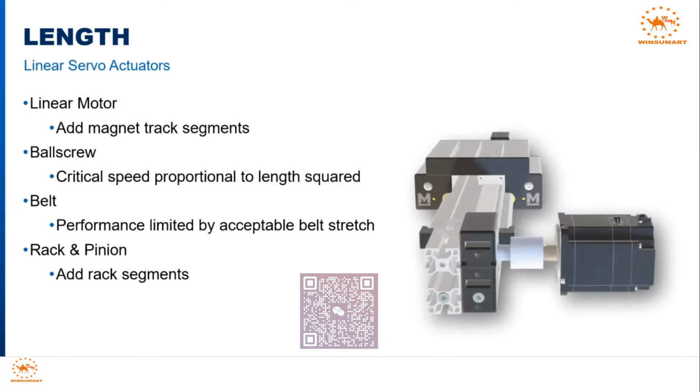Belt drive designs are easily lengthened with minimal increase in cost. However, the effective belt stretch becomes proportionally worse, resulting in reduced accuracy and repeatability. And like the ball screw, with increased length comes decreased stiffness and the problem of lower resonant frequencies.